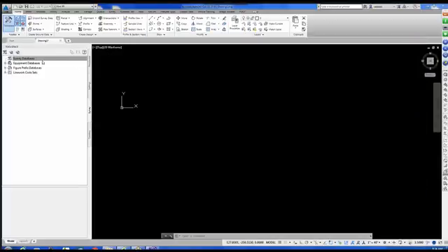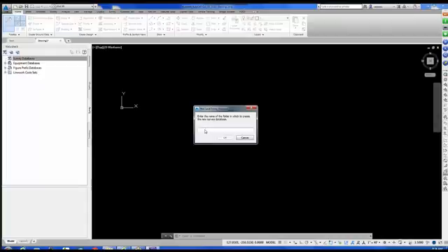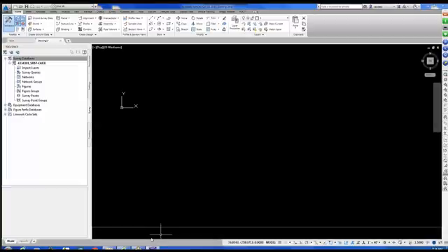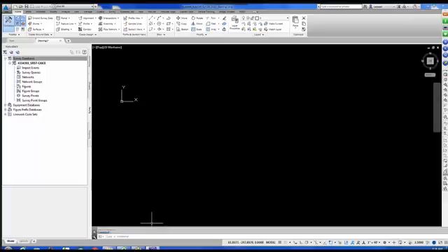Okay, my next step here is I'm going to right click and say I want to create a new local survey database. And I'm going to call this survey database 4334301_State Road 57 CAiCE. I'm basically putting the CAiCE at the end of it so that I know that the data type I'm working with is data that came from CAiCE. Right? I hit OK.